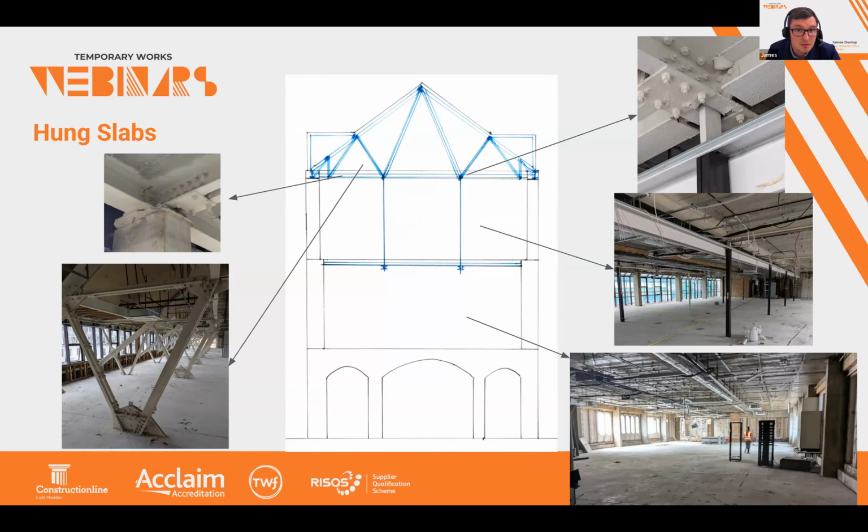as to how to demolish that safely, because when you take off the first floor, so you would typically demolish top down. If you did that in this instance, you would initiate a premature collapse, which, in some instances, if you're in a green field, it might be okay to do that, but that's not the case here. We've got other structures around us.